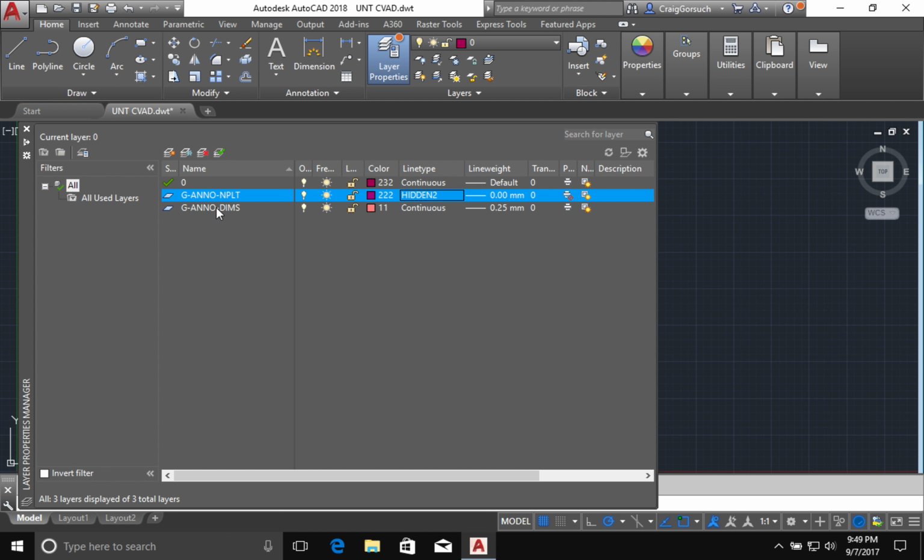So I'm going to go create all the other layers that are in this dialog. There's one correction that needs to be made. On the handout in this section on the left-hand side, there's a layer called GNOSYMB. It's listed as having a line weight of 0.25. It's supposed to be a line weight of 0.50.